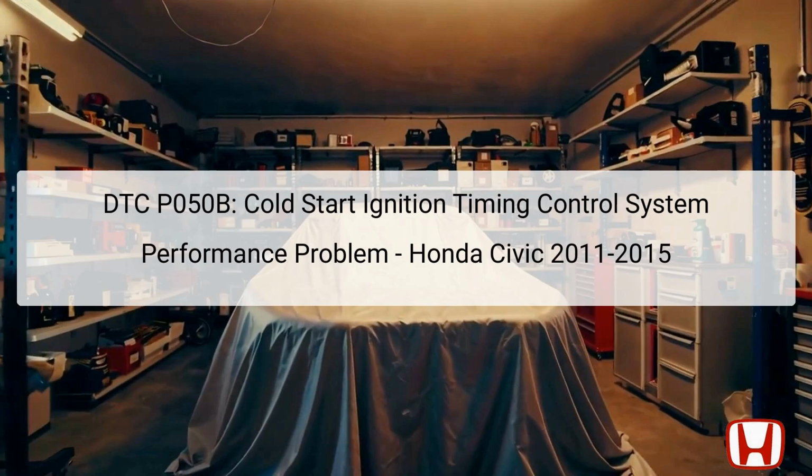The DTC P050B is an error code that indicates a problem with the cold start ignition timing control system. This system plays a crucial role in determining the correct timing for ignition during colder engine starts, facilitating smoother and efficient engine operation. If the timing is off, it can lead to rough idling, poor fuel economy, and increased emissions.